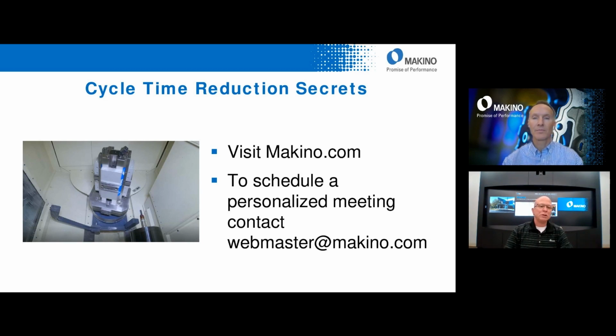G10 is a FANUC G code. It's a standard G code. It enables you to write to certain parts of the control. You can write to work offsets. You can write to tool offsets. Now on the FANUC side, you can write parameters. So you can change parameters on the fly, and you do that right in your CNC program.